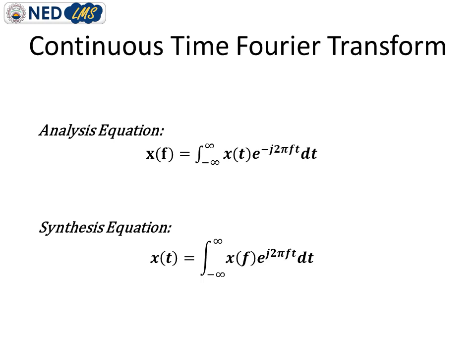The limitation of the continuous time Fourier series, which I have discussed previously, is that you can say it can only be applied to a continuous time signal, not a discrete one. So yes, it can be one limitation. The second limitation is that it can only be applied to a periodic signal, not an aperiodic signal. But the more specific limitation is that you cannot analyze any real-time signal with the help of CTFS.